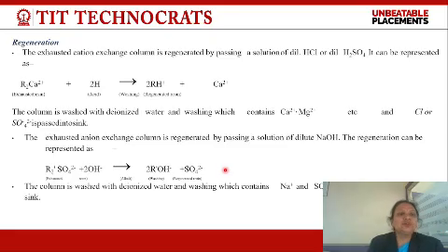So now I would like to discuss some differences between all three processes. As I already discussed, the lime soda process is simple. When we mix water, lime and soda together, the reaction proceeds, soluble particles convert into insoluble particles, and we can remove them from the water after sedimentation or after blow down operation.